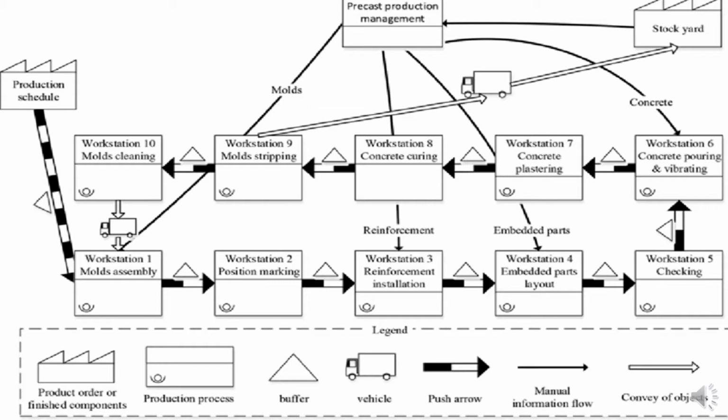Precast concrete being moved to the storage area. Stacking of precast concrete. Once an appropriate strength has been reached, the precast units are moved to the storage area. Units are usually handled within hours of casting as part of the rapid production cycle. The product exhibits a high degree of dimensional accuracy and quality of finish. Economies of production are achieved through the repetitive and automated process.